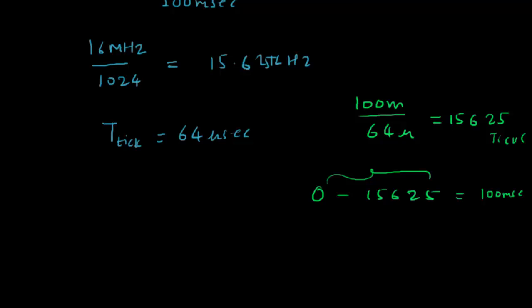Now, the timer overflows if the counter goes past 65,535, which is the highest count. So if you want the timer to overflow after 100 milliseconds, we need to subtract this count from the highest value.